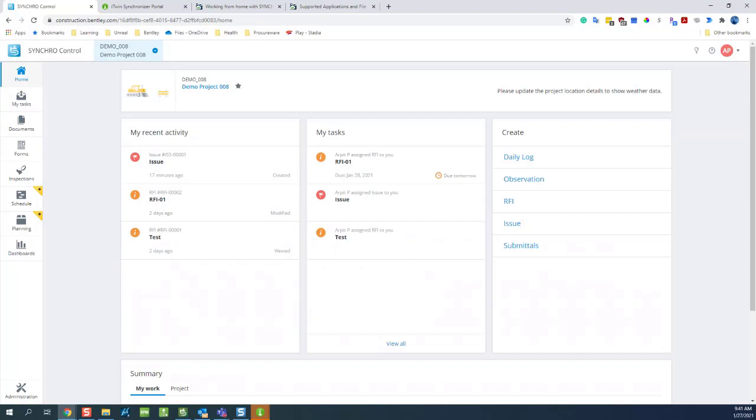Did I miss any question over here? So the only other question there is: can we upload a federated Navisworks model? And the answer to that question is currently no, we can't. We don't handle the NWD file format at the moment, but it may be something that we look to do in the future. And that's one of the limitations when you ask the question of SYNCHRO plugins versus the iModel bridges. In this case, you'll have to rely on the SYNCHRO plugin if you're committed to a Navisworks workflow. So that's another limitation there. But we are working on the iModel bridge for Navisworks, and that should come out shortly.